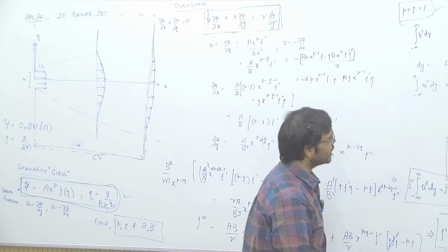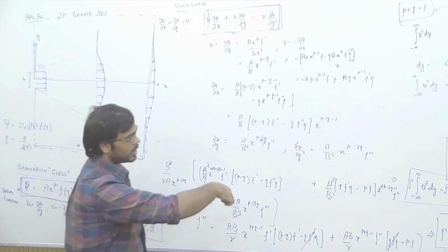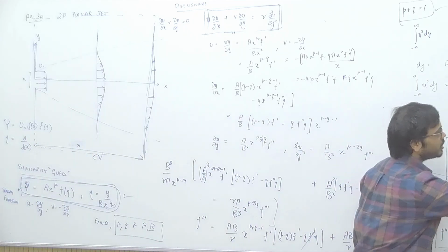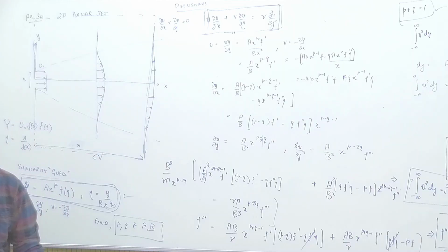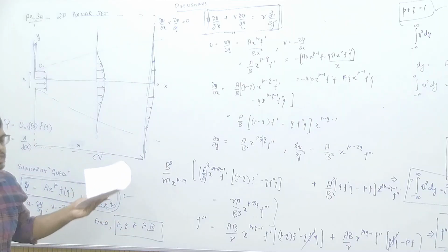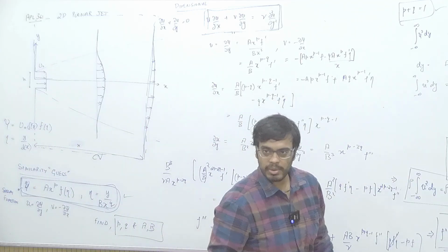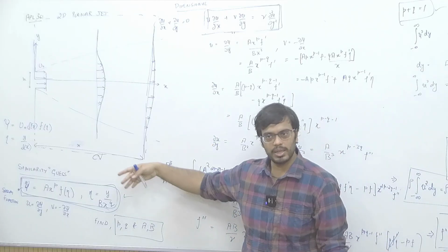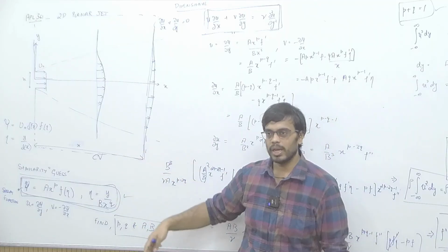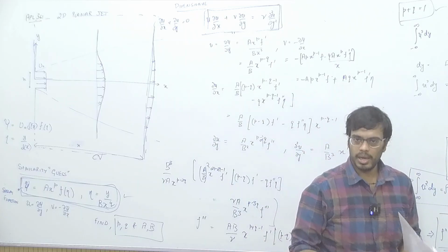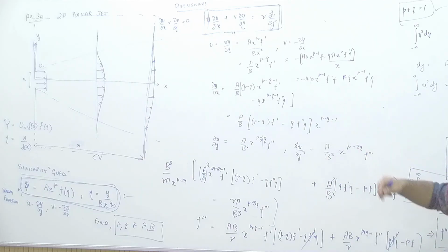So, there are more profound things that you can think about rather than just algebra: what do these exponents q 2 by 3, p 1 by 3 actually mean? What they mean is that the growth of this delta of x is faster than x to the power half because there are other physical mechanisms promoting it, in this case, because 2 by 3 is greater than half. If the exponent we had arrived at was less than half, then there are some other mechanisms which are demoting the growth of this boundary layer or whatever layer you are looking at.